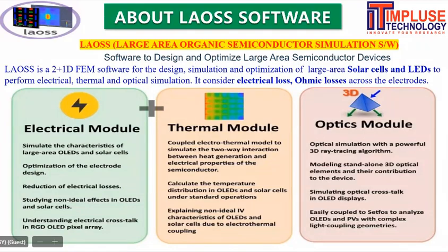It may get heated or overheated, so that kind of loss can be overcome, or some electrical losses may be there. The losses may be due to the geometry of your electrode, wherever you apply some biasing on the terminal. Suppose you have a solar cell, a PN junction, and you shine some light spectrum, AM0, AM1.5, or whatever spectrum. Whenever you are measuring its characteristics, there may be some losses. It could be electrical losses, thermal losses, heating, or optical losses.